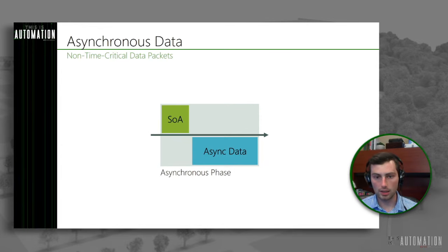Let's say you wanted to communicate some standard TCP/IP, but you don't want to have 2 redundant networks and cables. Instead of having an Ethernet cable and then another Ethernet cable for Powerlink, you can just combine those together and send that Ethernet data in that asynchronous phase. So it's a really powerful mechanism that allows you to leverage the real-time capabilities of Powerlink where it's needed, but also to leverage standard Ethernet or other asynchronous modes of communication when that data is not as time critical.